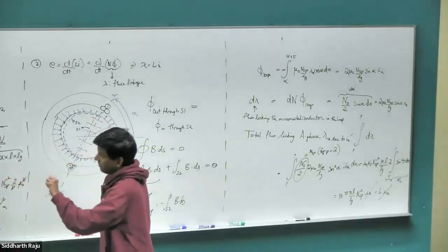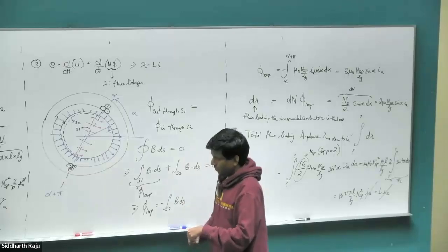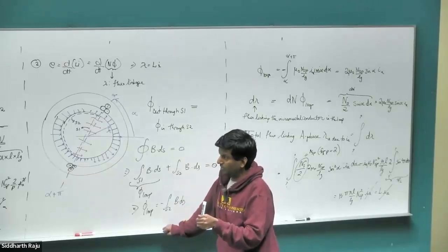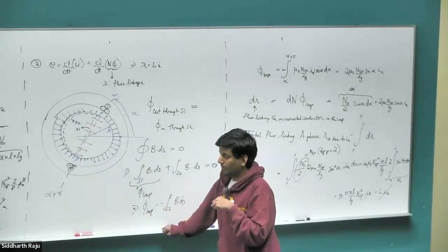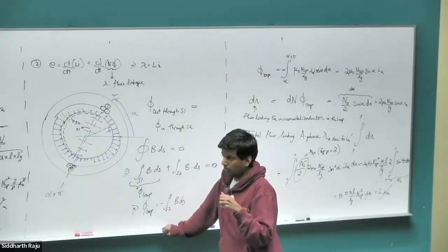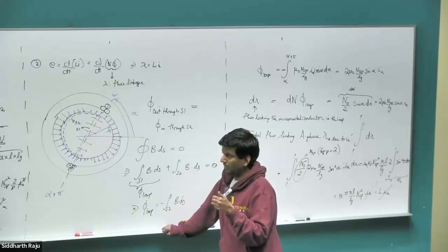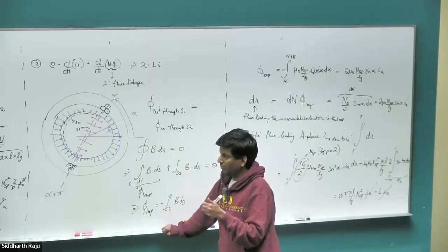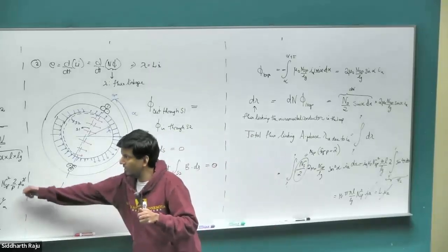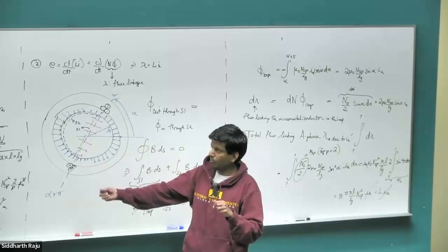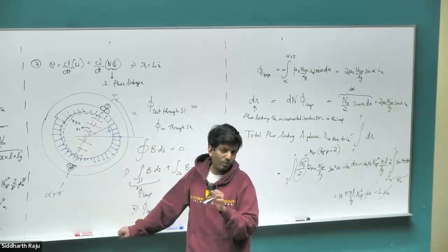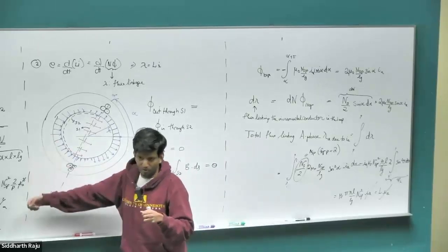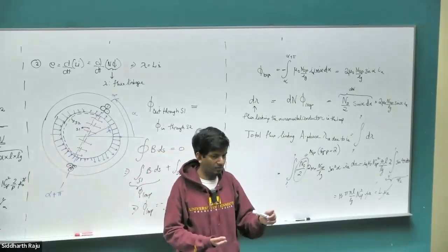So right now we are only considering sinusoidally distributed winding. In most motors, especially for lower powers, generators will typically be sinusoidally wound. But for EV motors and those that you use with a large pole count, the distinction between sinusoidal and concentrated windings starts to disappear. And there you would have to rederive these equations because the windings are no longer sinusoidally distributed. This only holds true for the distribution that we have. If the winding distribution changes in a different motor that you work on in the future, you go through the same process to rederive the inductance for that particular winding set, right?